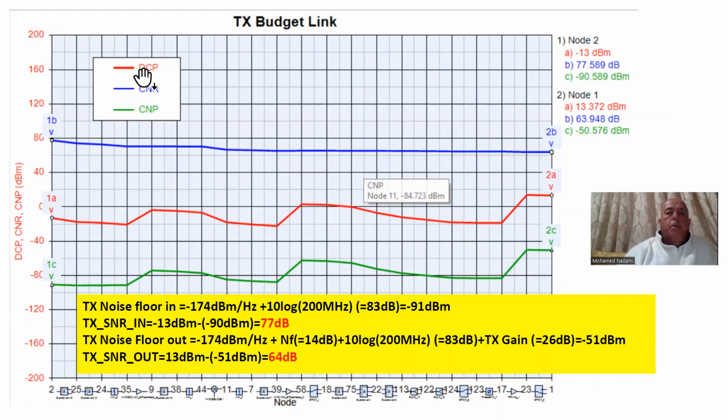So the desired channel power, DCP, is this here. You can trace a signal through this chain as it goes from minus 13 dBm all the way to plus 13 dBm, okay? And what I did here is trace the channel noise power and the carrier to noise ratio. Okay, so let's do that.